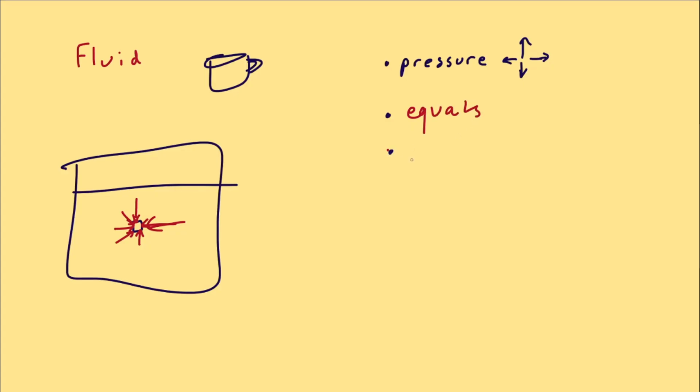The final thing is that pressure is always perpendicular to any solid surface. So let's say the force that pressure is creating is this way. This is perpendicular to the solid surface. But what if it was parallel, which is impossible if the fluid is at rest? If it was parallel, then Newton's third law says that it should create an equal and opposite reaction. So it would exert a force back on the fluid and make it move. So this parallel component of force from pressure is zero.